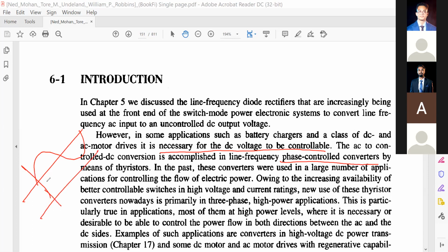Then we may get, okay, for the half wave rectifier, we will get this one, right? If you use the diode rectifier. But if you want to control it, you may get an output voltage like this. You may omit this portion. So this is omega T, and this is omega T. So this is pi, this is twice pi. So this is for the uncontrolled rectifier. You may control the output voltage like this. You may not want this portion.